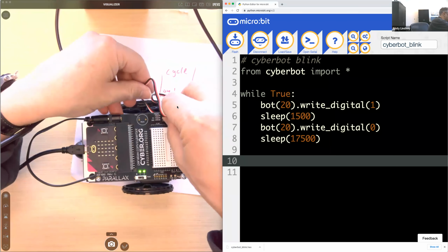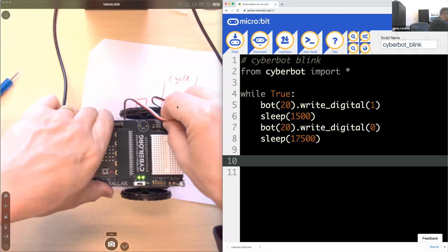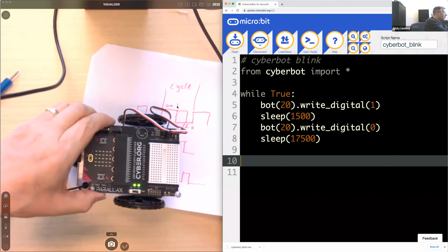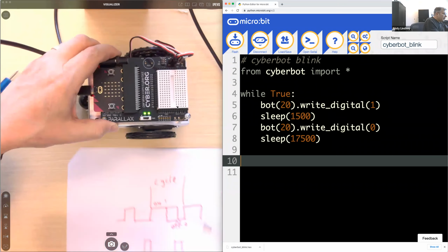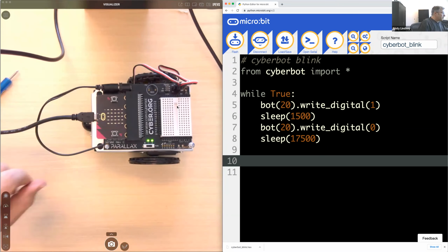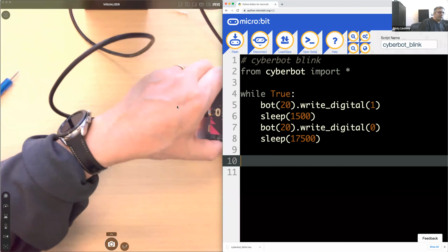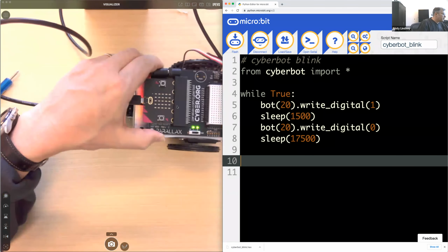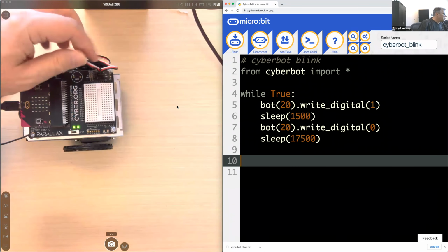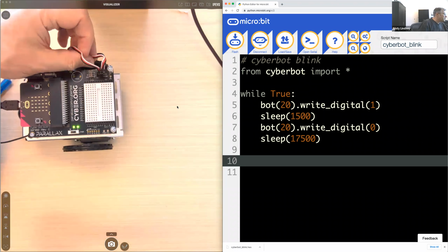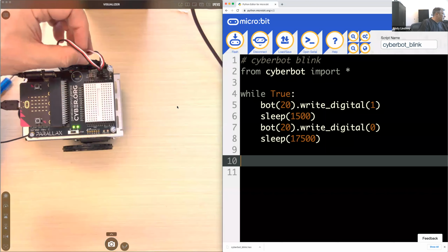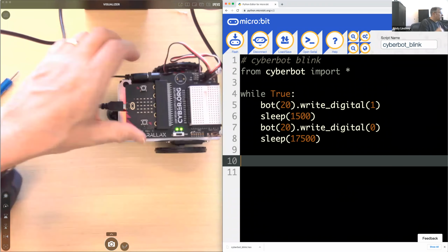Acting like I'm not following the instructions carefully, so I don't really know whether I did that right. And the answer will come when I run the script. Does it go forward for 3 seconds and stop? Or does it back up for 3 seconds and stop? So if it backs up, we'll know that these two cables are swapped, and they need to be unplugged, swapped, and then replugged. If it goes forward, we know they're good.